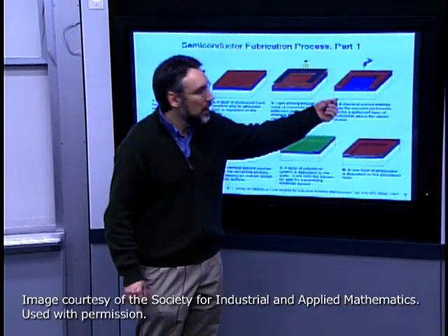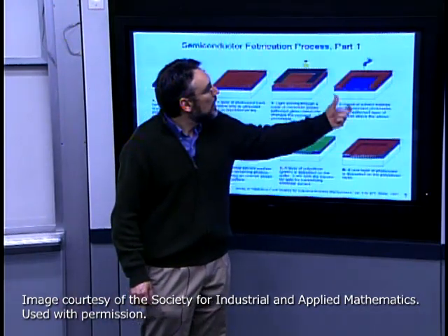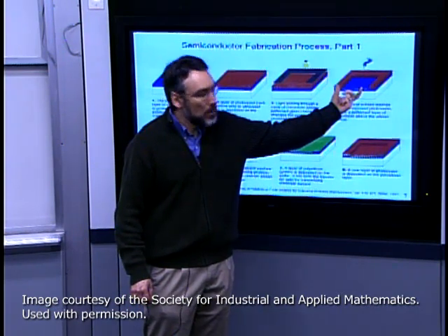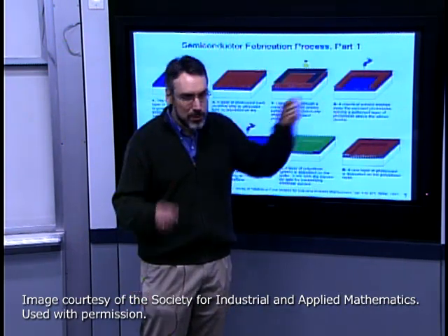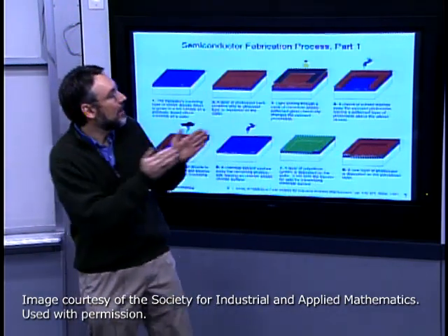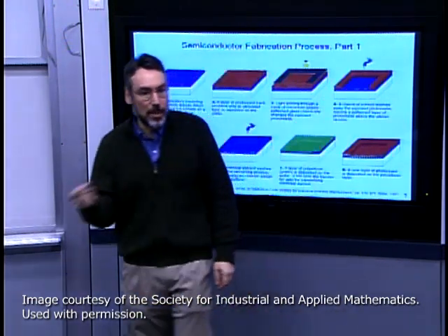Okay, so actually there's some degree of design choice in picking positive and negative photoresist depending on some manufacturing control issues. It turns out if you're developing away material, you might, in one case or the other, be able to actually overdevelop or overexpose slightly and control slightly the line widths of these features a little bit better in one photoresist case than the other, depending on what you want to do.